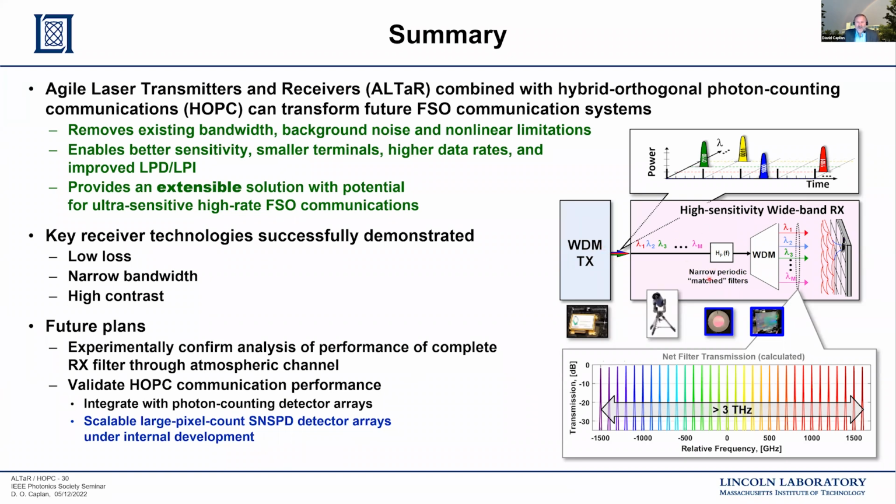Effectively it uses an IIR, or infinite impulse response, Fabry-Perot etalon, which can give us narrow bandwidth in a very small form factor. Our coarse WDM is only on the order of a couple centimeters wide on an edge, and it's giving us a 30 gigahertz bandwidth. In order to go to a 3 gigahertz bandwidth, I think we'd have to go to a diffraction grating that's on the order of 10 times larger.